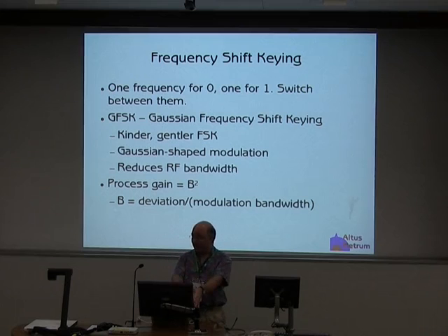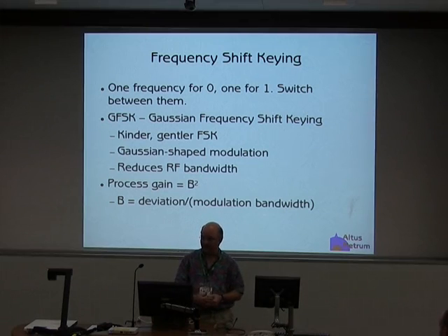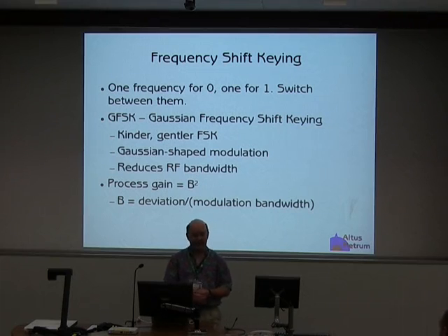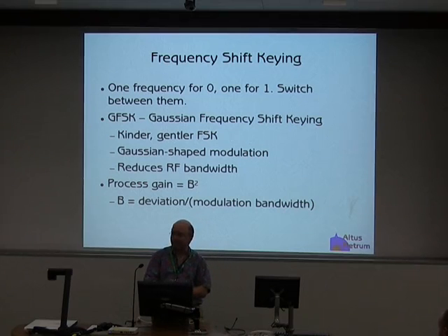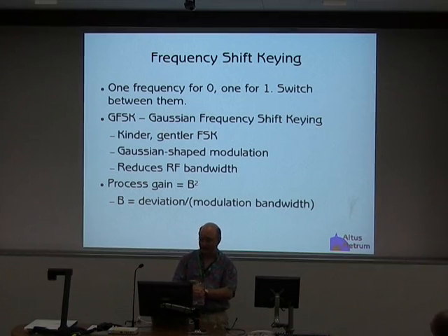Okay, so frequency shift keying is pretty good because you get this process gain. You only get the process gain if your raw signal to noise ratio of the signal is about 10 dB. Right, so the carrier to noise ratio of your raw FM signal needs to be at 10 dB before you start getting any process gain. And that's why for a really weak signal, you don't want to use frequency shift keying, because with a really weak signal, your raw signal to noise ratio is less than 10 dB, and all of a sudden your process gain starts to turn into process fail because you actually start losing your FM capture, and all of this disappears and your FM signal goes into the mud and you get no signal out.